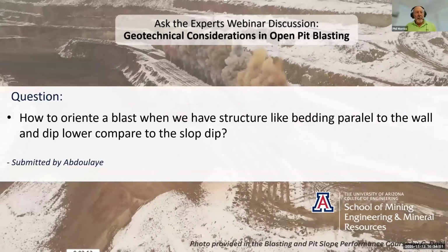I think some of the issue that you guys are talking around here relates to the fact that the slope design in the mine plan has probably got a pre-split in there, and it's a 70-degree BFA when you've got a 41-degree bedding dip out of the face, and it should never have been there, really. There are some situations where pre-splitting is not the solution, and obviously there's a critical angle at which the Mohr-Coulomb criteria mean that it doesn't matter what your cohesion is.